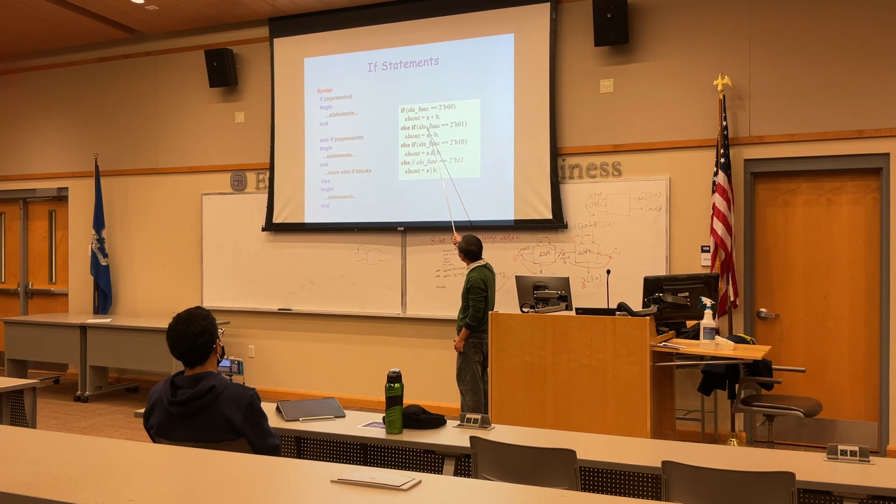Else if this mode selection signal is 0, 1, we have to perform subtraction, send to output. Else if the function mode is 1, 0, then I have to perform an AND function, send to output. For all other cases, for example, we use A or B, send to output. It's always a good habit to have an else.